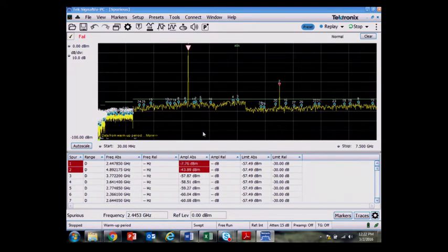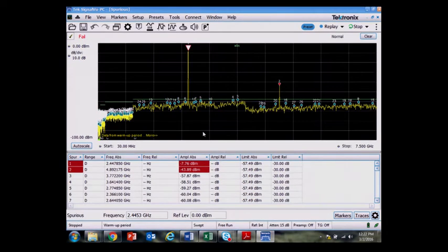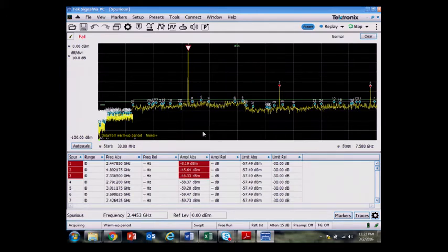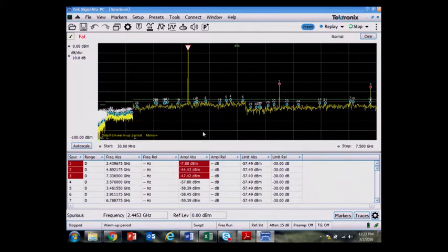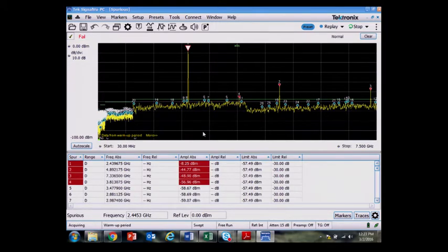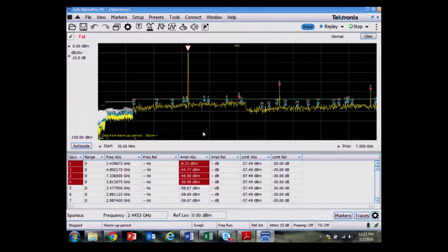This is typically a test that would be done over a broad frequency range. You can see this is done up to 7.5 gigahertz for EMI pre-compliance. As long as I have the setup done correctly, I'm in some sort of quiet RF environment, and there's not background noise that's interfering with this, then this should give me a reasonably good assurance that I'd pass the test.